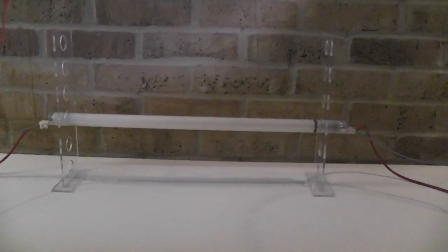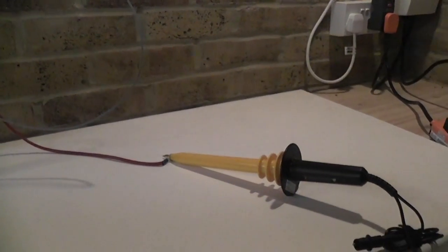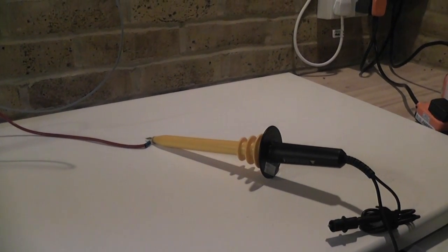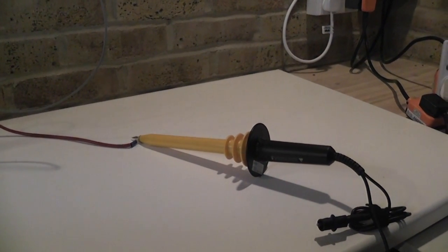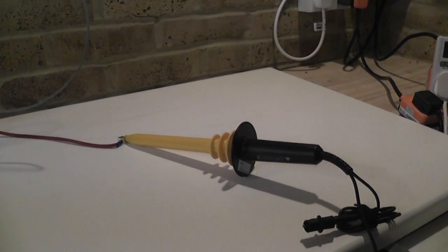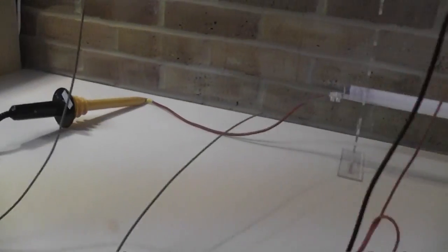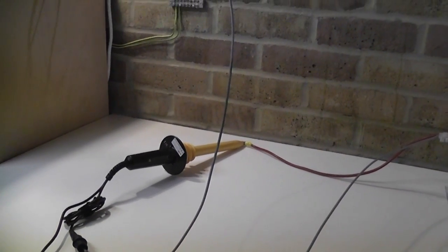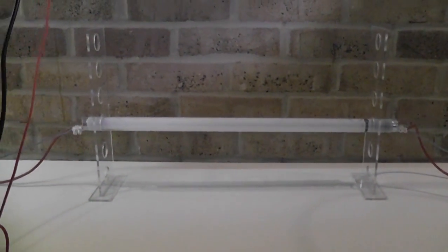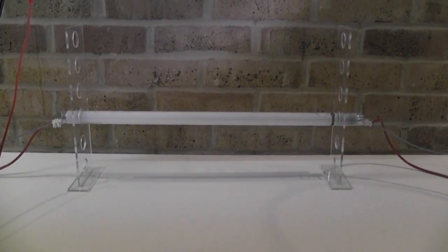So what we have to do here is measure voltage on both sides. We have high voltage Agilent oscilloscope probes with extremely low loading, 7 picofarad. I use 2 of them, 1 on each side. It gives me a voltage propagation based on the frequency on each side, and that will become apparent. It's quite interesting to see what's going to happen.